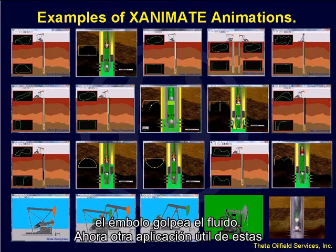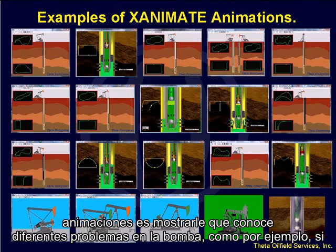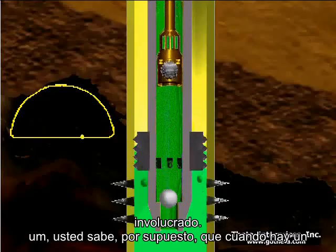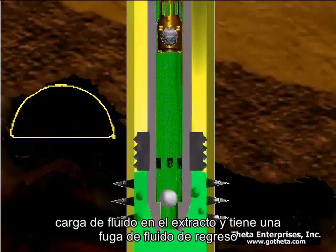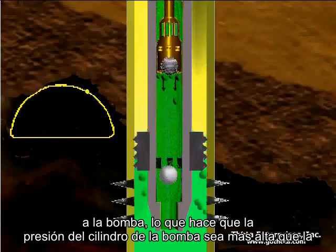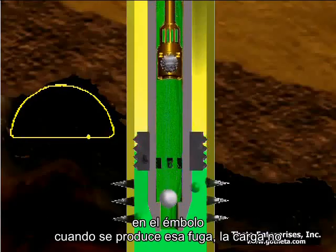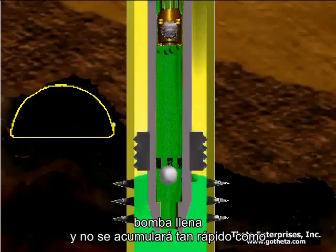Now, another useful application of these animations is to show different problems at the pump, like a leaking traveling valve, for example. This animation shows what happens when you have a leaking traveling valve. Of course, when you have a leaking traveling valve, you're losing fluid load on the upstroke, and you have fluid leaking back into the pump, which makes the pump barrel pressure higher than it would otherwise be. Since the pressure difference across the plunger is what determines the load on the plunger, when that leakage occurs, the load is not going to be as high as when you have a full pump, and it's not going to build up as fast.